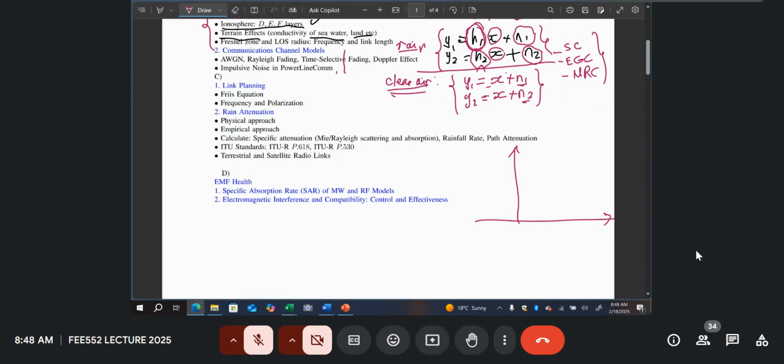Let's say we have the signal power or signal to noise ratio, and we are trying to determine the bit error rate. Let's say the modulation type that we are using is binary phase shift keying. This one just has 2 symbols, so you're only transmitting 1 bit. You could also check QPSK. These are 4 symbols, which is 2 bits.